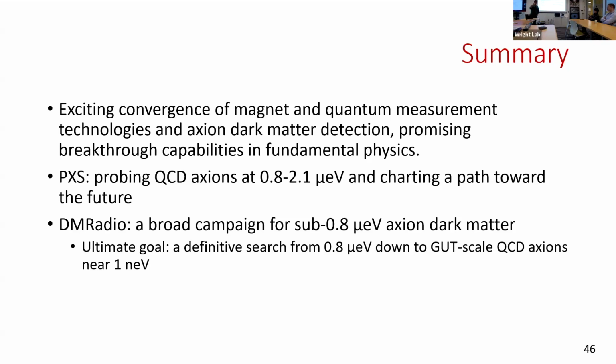Gotcha. And so there's a copper sapphire heat sink there to pull the heat away. I have to double check, but I think it's roughly 40 watts. And then the HTS leads, they actually have some amount of silver in them. So the heat flow through them is about 240 milliwatts. So that also needs to be heat sunk to just remove the heat and not have very high gradients. So I'm not sure if that answered your question.